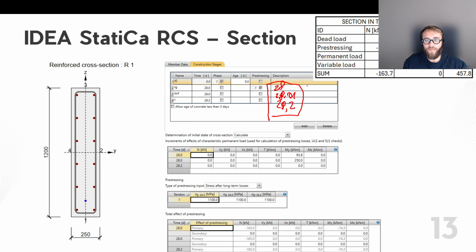That time frame is very close, so there will not be differences in the results from the point of view of the losses. And as I mentioned before, the creep and shrinkage are turned off, so they will not be involved in this calculation. You also need to bend the software a little bit, removing the creep coefficient in RCS to emulate the behavior you want.